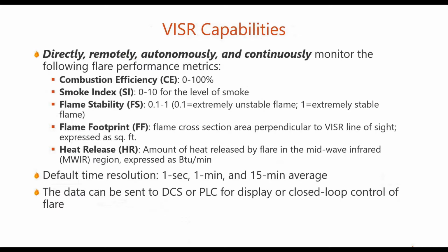And this data is provided with no latency. So it's immediately available for consumption either by DCS or PLC or a user interface provided with VISR. These performance parameters are calculated in real time with no latency, so it's very well suited for a control loop. A VISR system can actually be put into closed loop control and used as a feedback system to enable automated control of optimization of your flare.